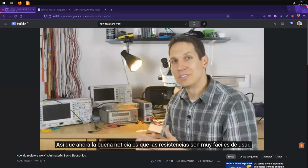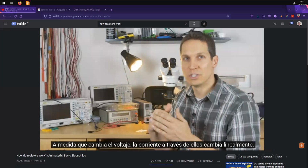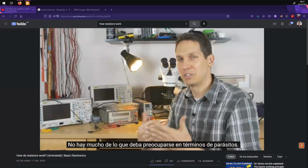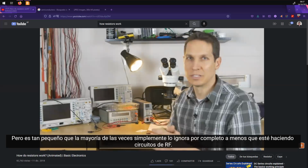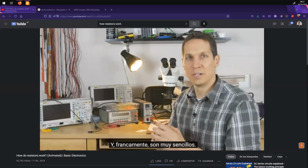So now, the good news is that resistors are very easy to use. They're highly linear as the voltage changes. The current through them is linear, and there are few parasitics. There's a little bit of inductance and a little bit of capacitance, but it's so tiny that most of the time you just completely ignore it, unless you're doing RF circuits. And frankly, they're just very straightforward.